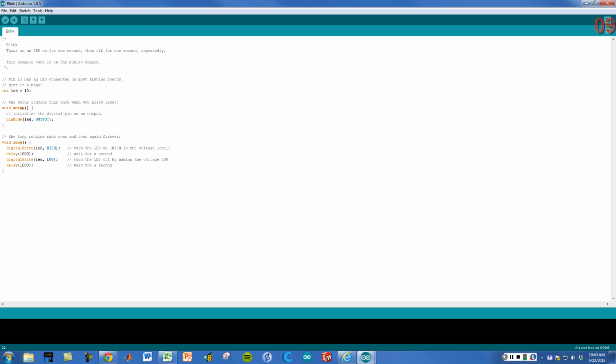Notice we've used comments for each line of code just to tell us what it does. So double slash, and all of this out here in gray is just telling you as the programmer what your program's doing. Arduino ignores it. So in our void loop, we've turned it on, we've delayed 1 second. We've turned it off, and then we've delayed 1 second again. Now you're ready to turn it back on, so you just close your void loop. It will come back up, and it'll run that over and over and over. So that's our first code.